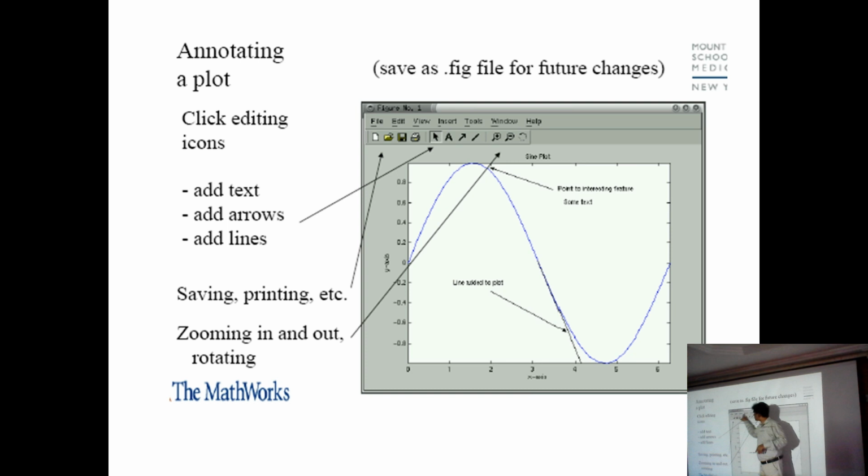The meaning of all these shortcuts is that after plotting the graph, from the figure window itself, you can edit it. If I don't know the command for xlabel or title, I can use these menu options and add whatever I want. For example, I want to add the title to the axis. From the options, I go to edit, and there will be several icons.